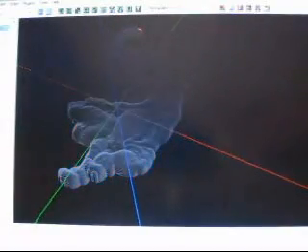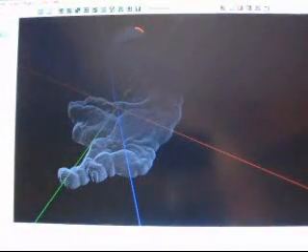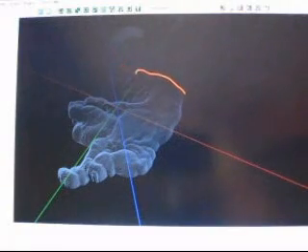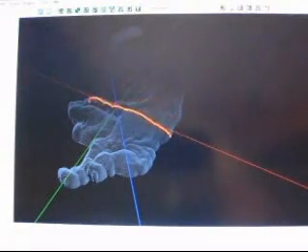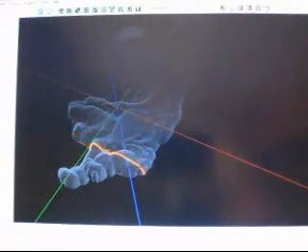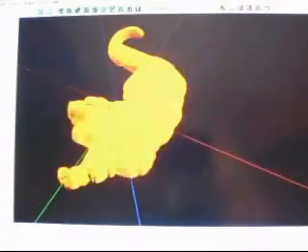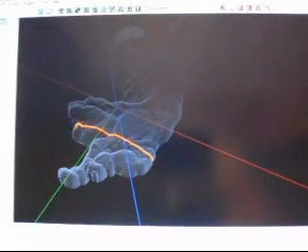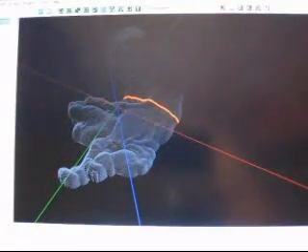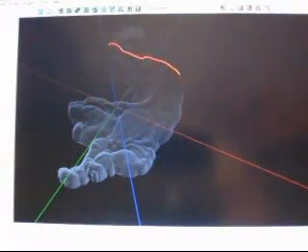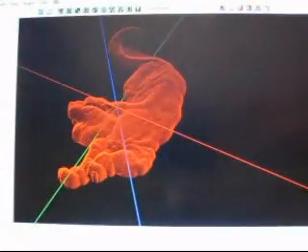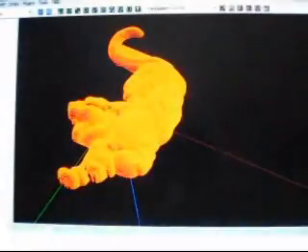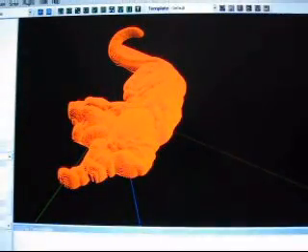And here's all of our polylines. As you can see, we got a ton of polylines, but it's not like having a million teeny tiny lines. So we're going to get predictable results when we run an engraving program on this. That's the key thing. We want predictable results. We don't want a bunch of nonsense.